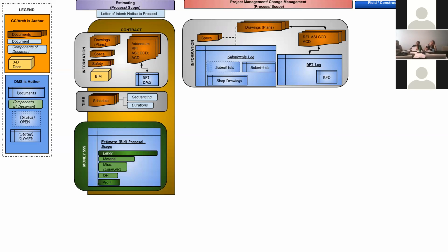Example would be, let's say they moved a column over 2 feet. You might think, oh, it's a structural column. That isn't going to affect us. However, that structural column has now rerouted the walls. So it looks like the structural trade gets mostly affected, but it's now relaid out the walls into a different way, which does affect us because we're the walls and ceilings builders. And so we might ask additional RFIs.